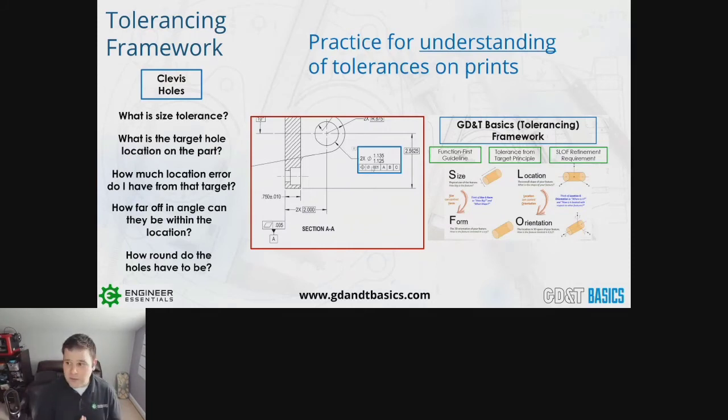And then you have to come in though, and you have to make these considerations as well, because this is all about function. If I don't hit this 0.001 in position with this, the pin that goes between there might be offset enough where I get a bending moment on my piston and it snaps off after 1,000 uses, right? So there's so many considerations that we have to make as designers, and we have to communicate that information.